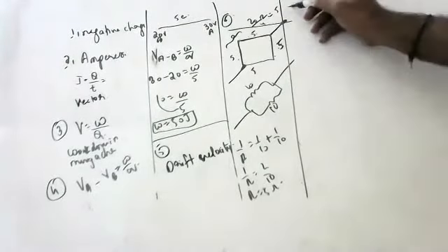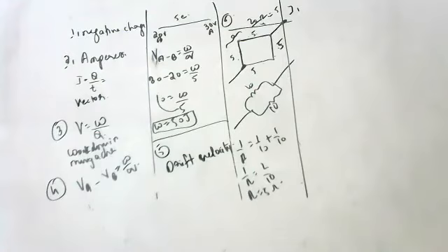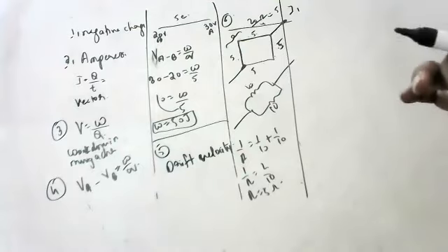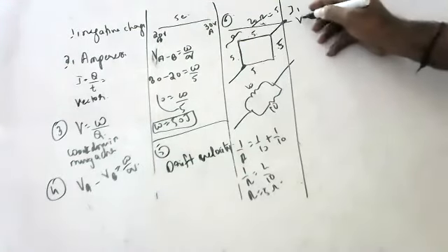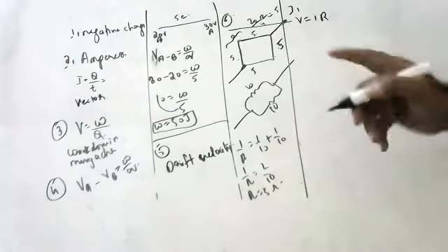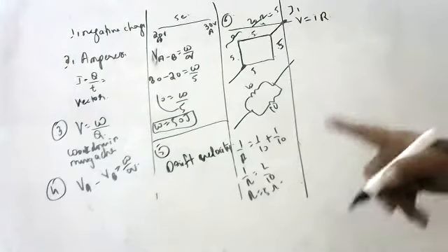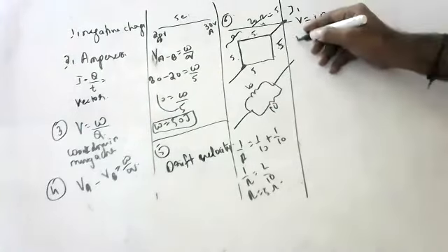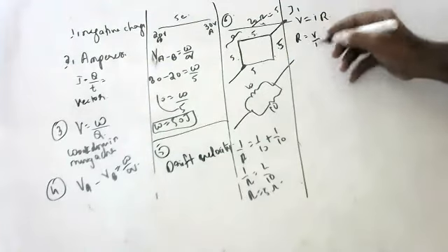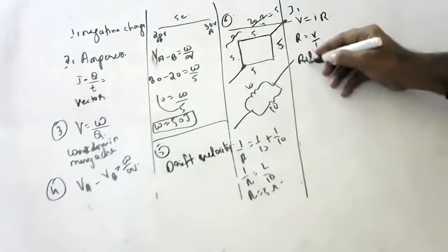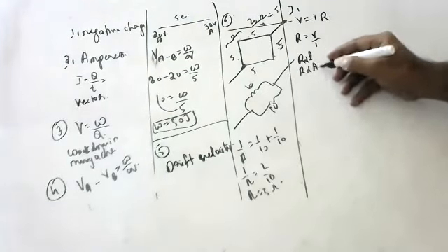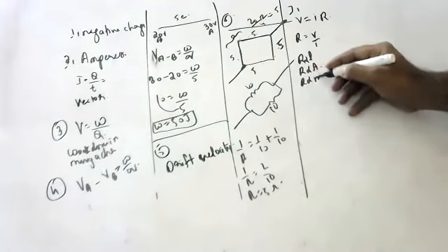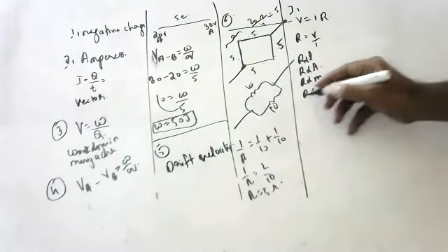Next question, children. Seventh question. How does the resistance of a conductor depend on voltage? Normally, V is equal to IR. Okay, children, resistance does not depend upon voltage, remember, because resistance is constant. R is equal to V by I. Resistance depends on length, area, material, and temperature.